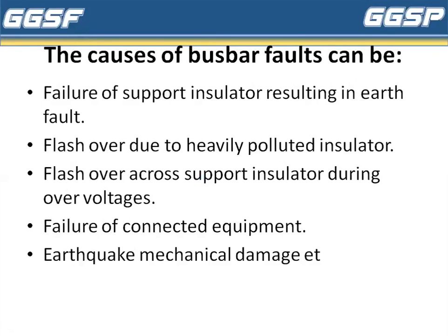The causes of busbar fault can be: first, the failure of support insulator resulting in earth fault. Second one is flashover due to heavily polluted insulator. Third one is the flashover across the support insulator during the overvoltage. Fourth, failure of connected equipment. Fifth is earthquake, mechanical damage, etc.